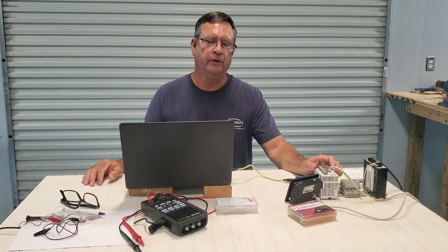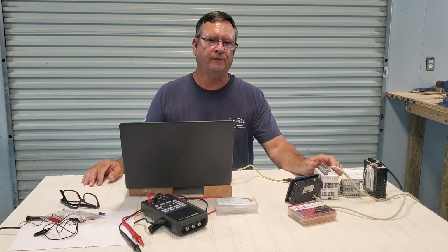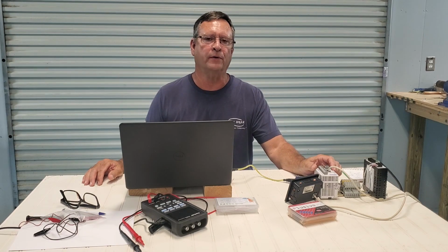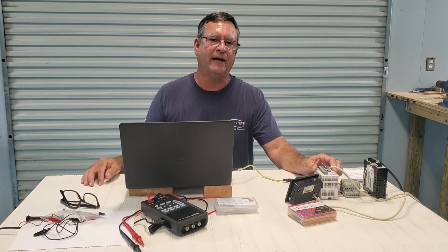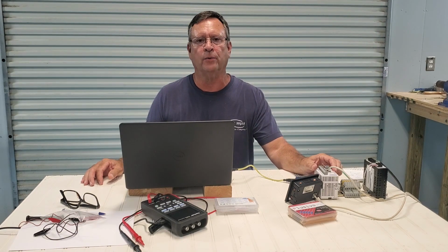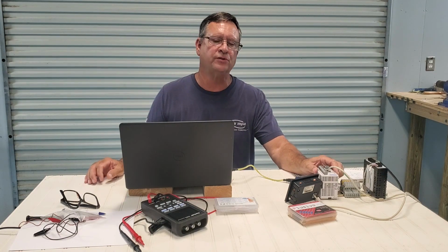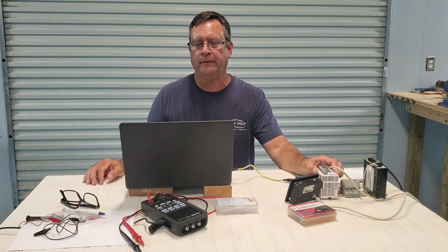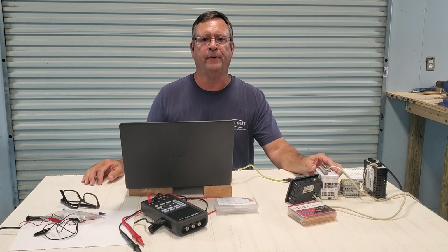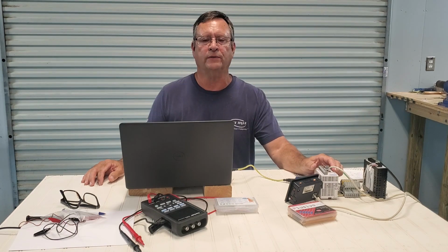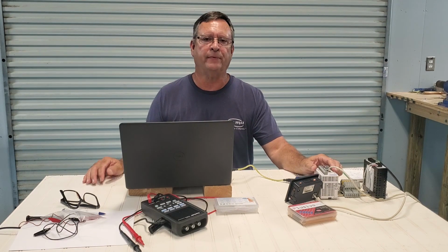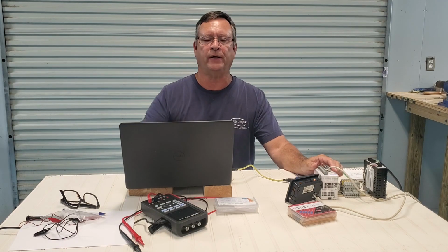But what's really good about this program is it's a perfect example of using a for next loop and pointers to increment data addresses as you go through, especially when you're searching for a value that you've already set in there. Now, I did have to use a spreadsheet to come up with the values that I wanted to put in, because I needed to know what value I expected for each temperature at the analog input. So that's just simple Ohm's law, but I showed you how to do that in this video, and also used a spreadsheet so that once I developed it one time, I could just grab the value and drag it straight down in the spreadsheet.